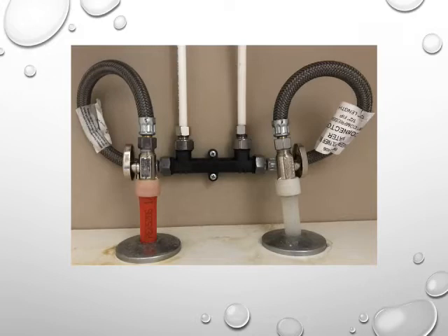And so as we saw, when that timer tells the pump to turn on, this is a nice little valve gizmo that allows the water to flow straight through to the cold water side. So we've got hot here on the left, cold on the right. It's got this nice little thermostatic valve inside there so that once it reaches the temperature, it actually turns off. That way you've got that hot water there when you need it, and you're not constantly heating up the cold water side. When you turn the cold water on at this particular sink, if you happen to do it right after the pump turns off, the cold side might be a little warm for just a second or two.